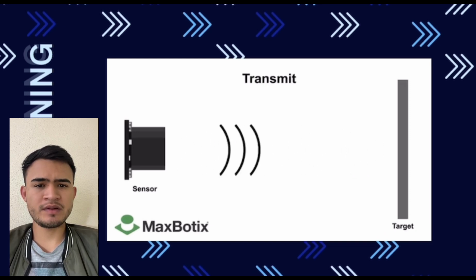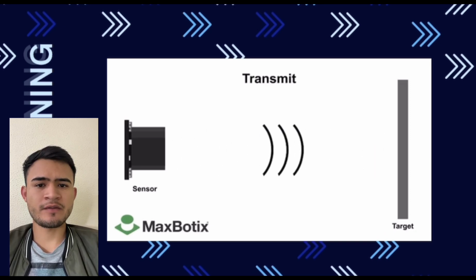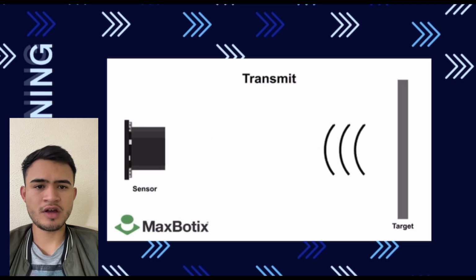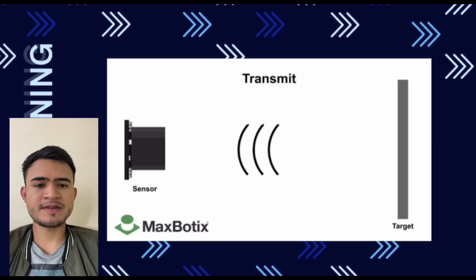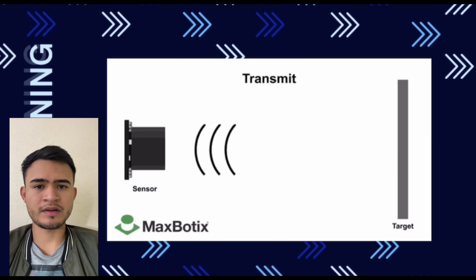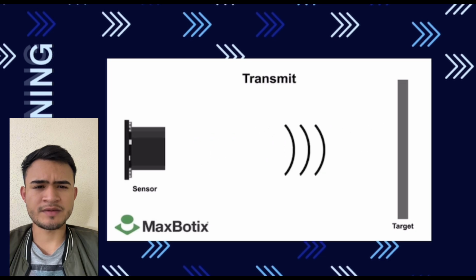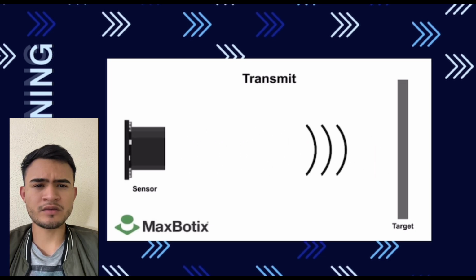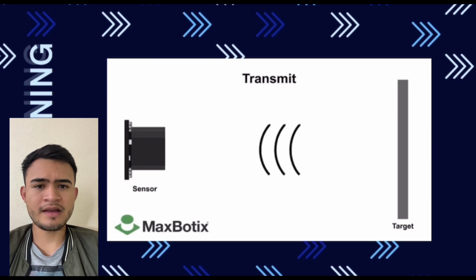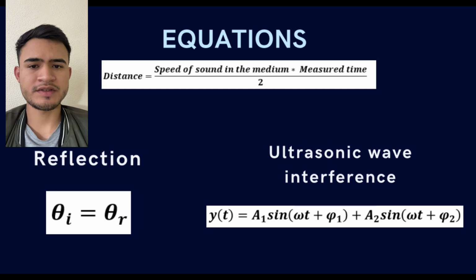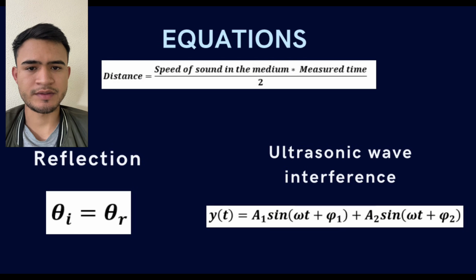The trigger pin receives the signal from the Arduino, whose task is to send a sound, and the echo pin receives the signal when it returns after colliding with an object. It is sent to the Arduino and the distance is calculated with speed and time, an effect like that of an echo. Here we have the equations that mathematically explain the operation of the ultrasonic sensor.